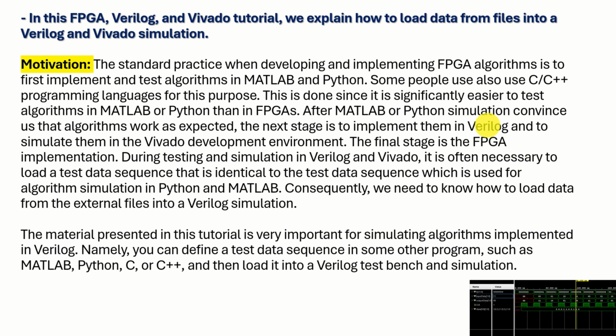After MATLAB or Python simulations convince us that algorithms work as expected, the next stage is to implement them in Verilog and to simulate them in the Vivado development environment. The final stage is the FPGA implementation. During testing and simulation in Verilog and Vivado, it's often necessary to load a test data sequence that is identical to the test data sequence which is used for algorithm simulation in Python and MATLAB. Consequently, we need to know how to load data from external files into a Verilog and Vivado simulation.